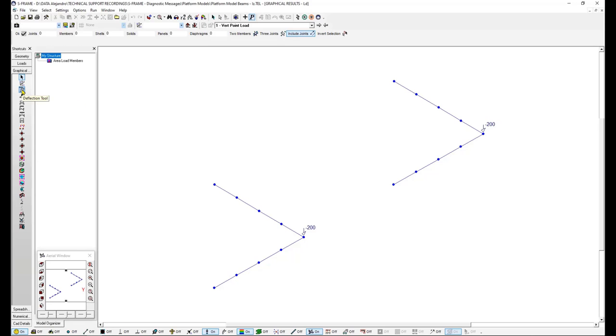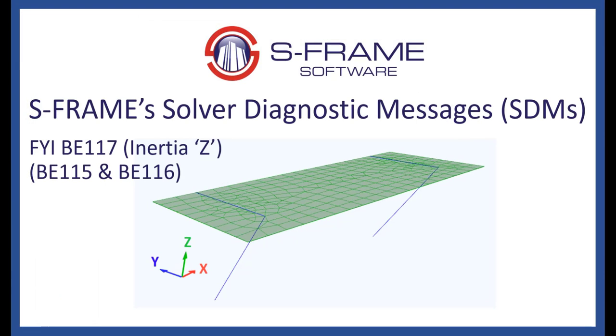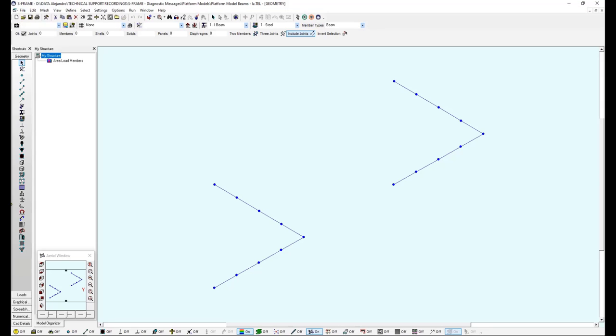When I come to the results and see the deflection tool, I display this value. Just let me hide the joint load. I see some reasonable values, about 4 millimeters in the Z direction. Results seem okay, and I finish for now. Now, let's imagine that I go on holidays for 2 weeks, and I close this model. Once I come back, I open my model, and my manager asks me to see the response reactions and deflections for the structure subjected to a horizontal load in the x direction.